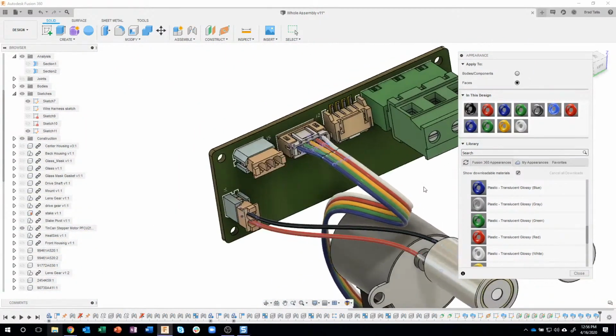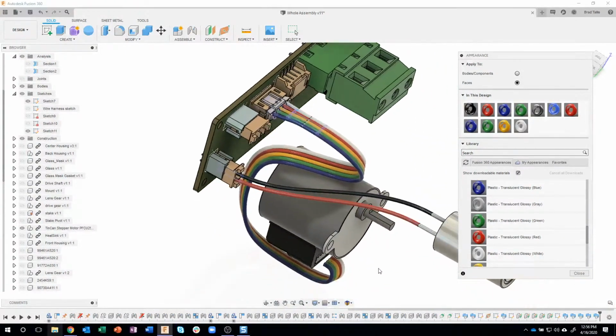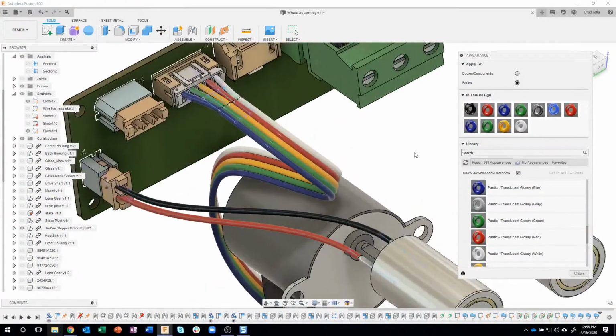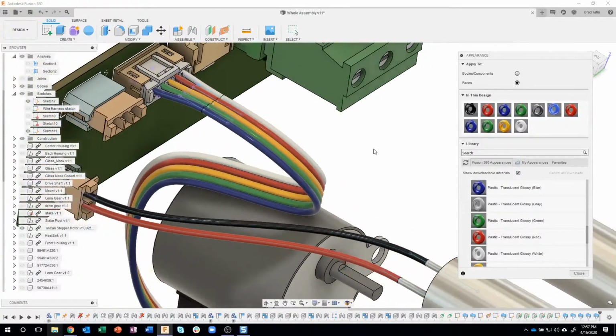And now I think it looks like a really cool ribbon cable that would look really nice in renderings and all that kind of stuff. So this is the basics of creating wiring right now. We create a spline, we can use our new 3D spline technology, and then we're just sweeping profiles, whether it's a circle, or a pattern to make a ribbon cable. I could have done a pattern of circles around the center and made a twisted cable. It's really up to you.